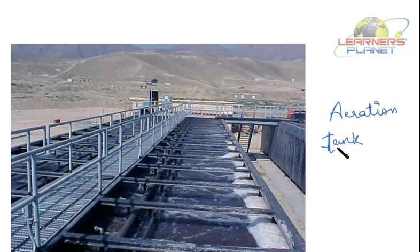This biological process is then followed by additional settling tanks, which is also called secondary sedimentation. Right? So here more of the suspended solids are removed, and about 85% of the suspended solids can be removed by a well-running plant with secondary treatment.